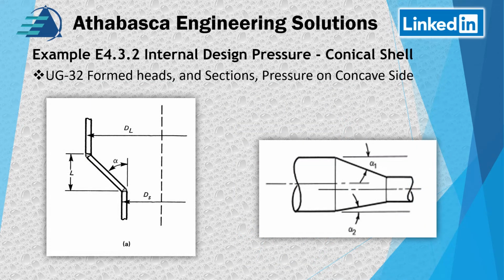So let's go back and take a look at UG-32 and look at the spec. So formed head sections and pressure on a concave side. What we have here is some definitions of the dimensions. L is for large, S is for small, and ASME uses those pretty universally.